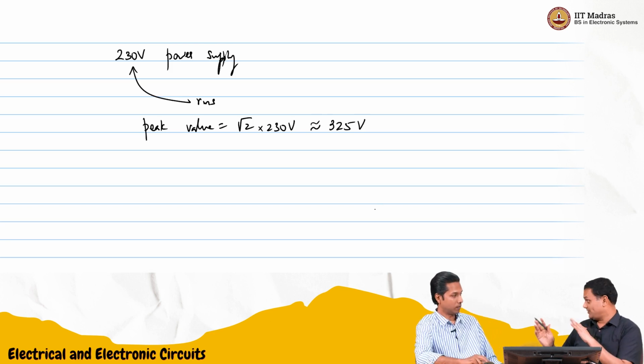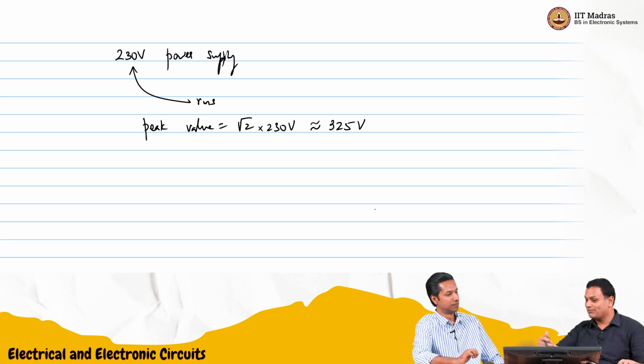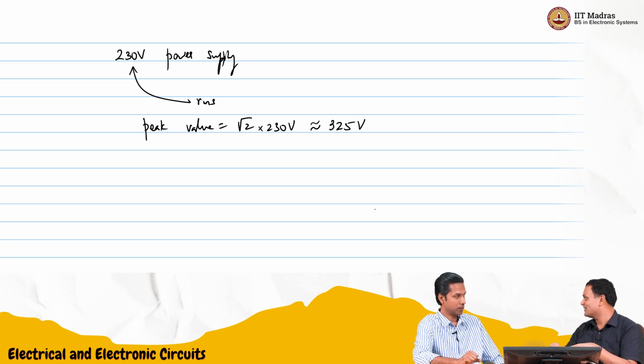Students should not try this with their oscilloscope, because it can't handle 230 volts. Only fumes will come out. But if you take an oscilloscope that can measure up to this power, you will see the sinusoidal voltage with a peak value of 325. If you look carefully at digital or analog multimeters, they will tell you whether you are measuring the RMS value.